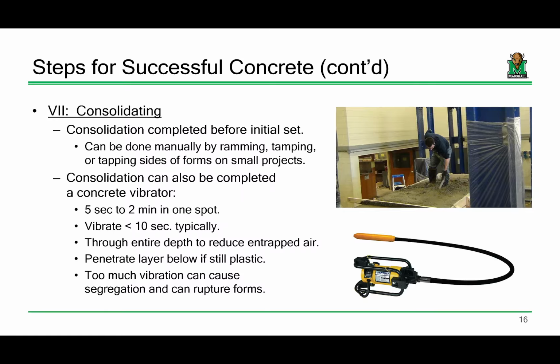So in the lab, we were using the 3/4 yard bucket to do this. There was a concrete truck that had pulled up to the back. We filled the bucket up. The lab had an overhead crane that did that. We placed the deck in, I want to say, 4 or 5 trips of the crane. So we actually had the concrete in the forms in about 25, 30 minutes, something like that.